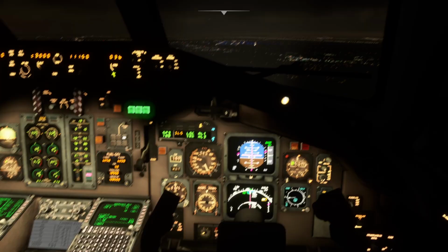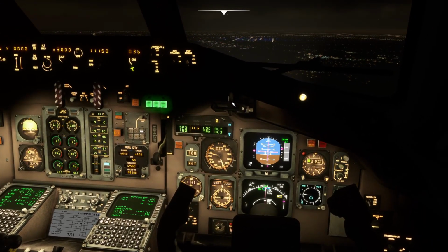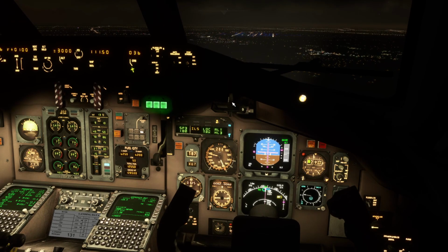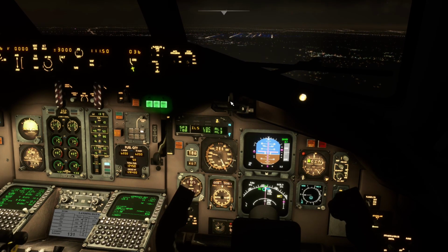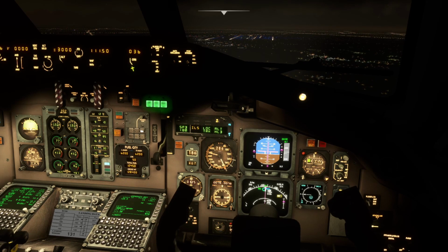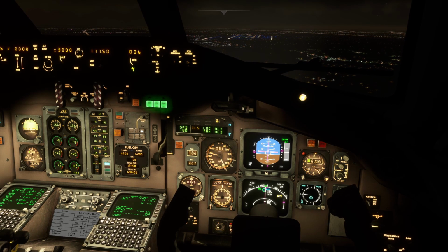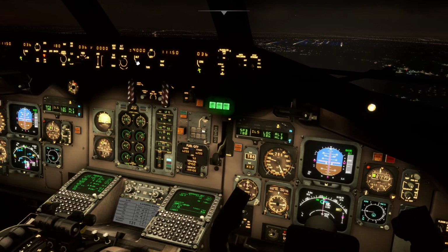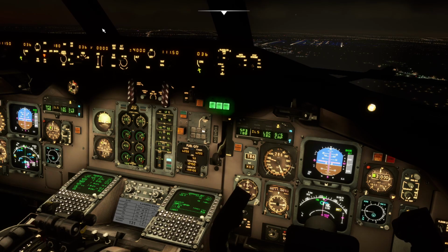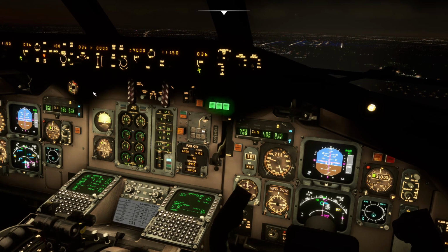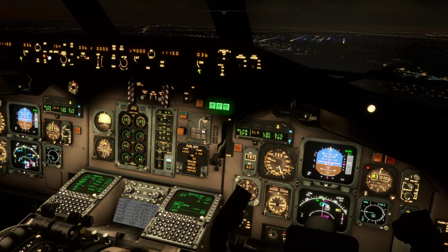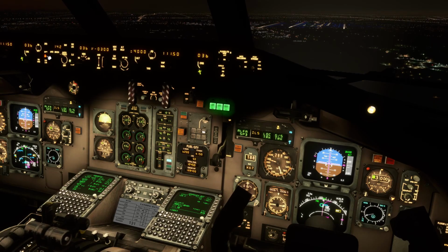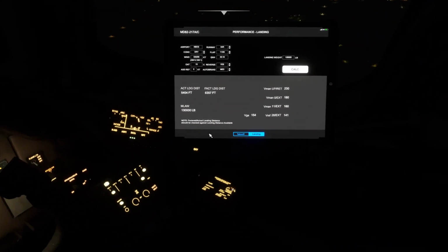Alright, we'll bring up flap 15. Once we hit the glide slope, I'll bug the VREF and set flaps 28. Hopefully it should grab it. Let me just double check my approach altitude was 4,000 feet, yeah. Come on. There we go. Glide slope capture. Very good. So now we can bug the VREF, which I believe is 141. And flaps 28.